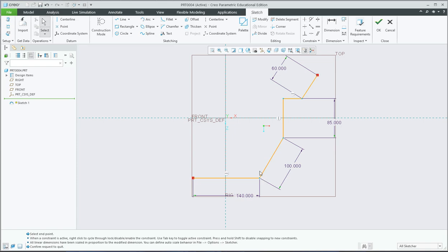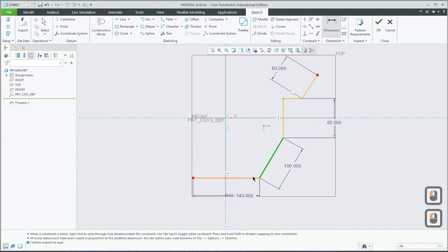And then according to geometry, supplementary angles of straight lines will be equal to 180. So this is 120 over here, then the angle over here should be 60 about this horizontal line. So step with measurement, select this line and that line, but this time I want to put the angle here outside. So make sure that you point here and then middle click. And then you're going to see that it's 60, press enter. All right. So wherever you middle click is where the angle will be placed.